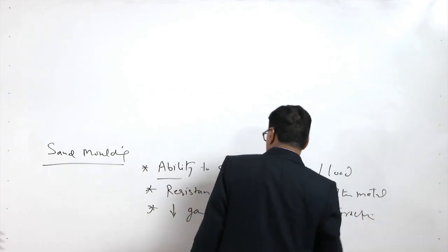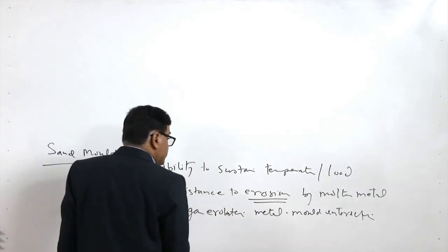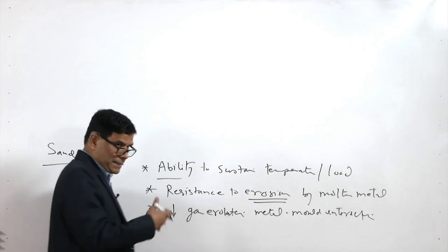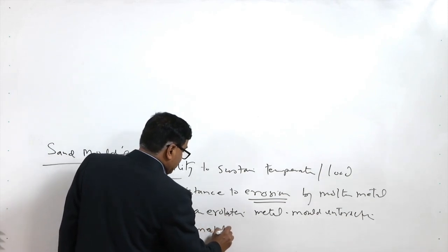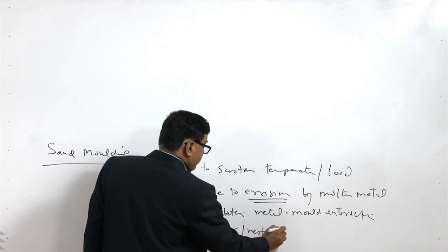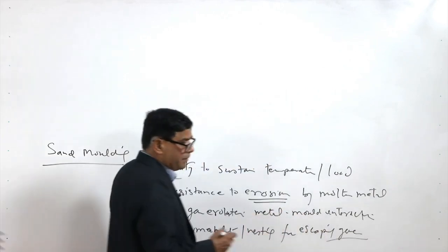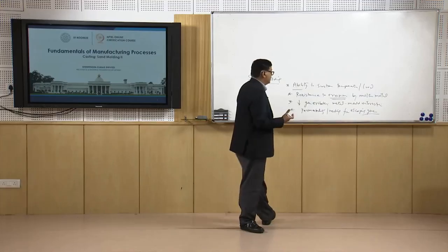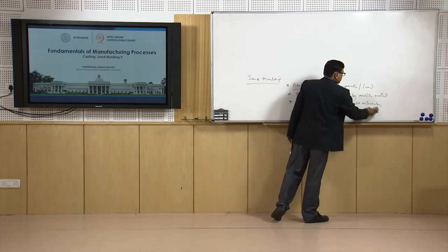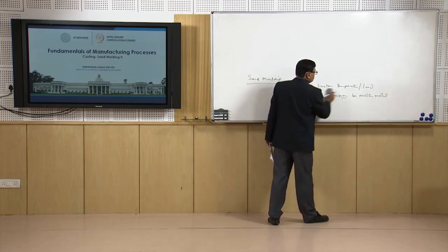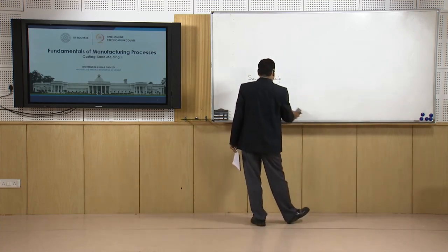So, undesirable gases should not be generated much due to mold-metal interactions, and even if these are generated, or even if gases are present in the mold wall, it should provide enough permeability and venting for escaping of the gases, so that undesirable gaseous defects like gaseous porosity, inclusions, blowholes, etc., are not formed in the casting, which would ultimately make the casting sensitive to defects.